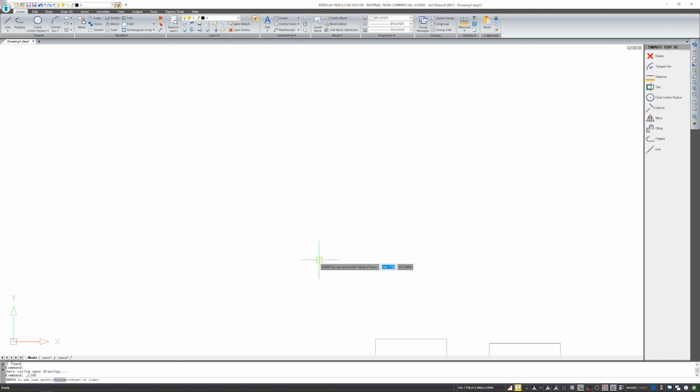You can use the tab and input window to draw angles, but you don't have to, and you can select options from under the arrow. You have probably seen the angle and the length under the arrow and at the bottom of the screen. It was shown in the previous presentation, so just a reminder. Here you can choose, for example, the length. I specify the length of 200, confirm with enter, and now we enter the angle.